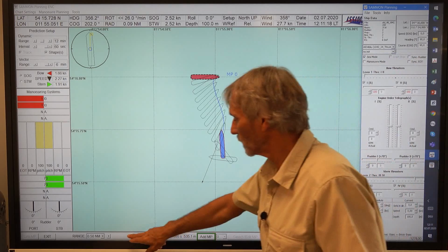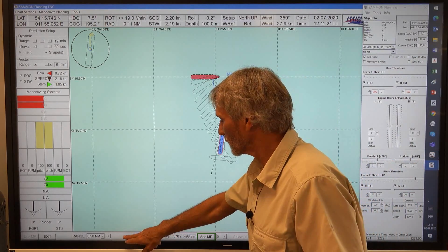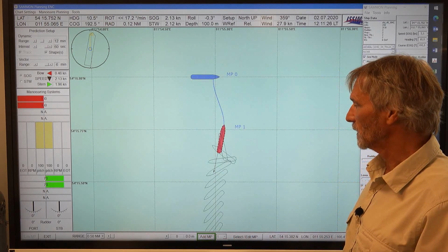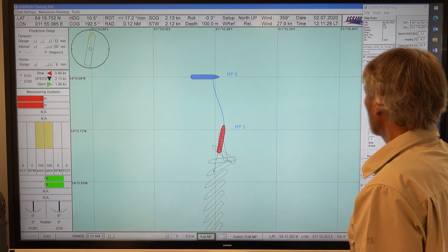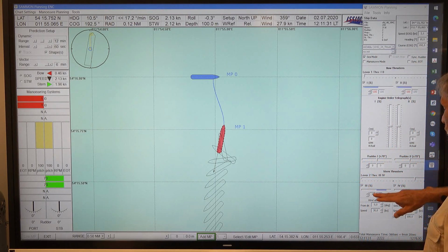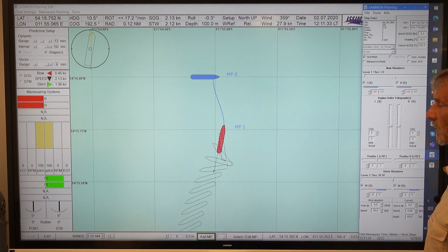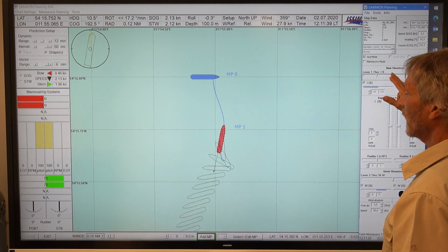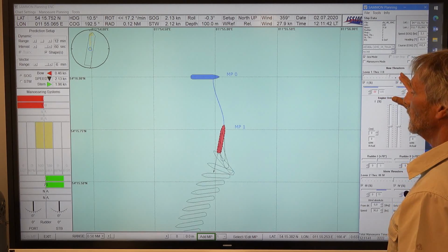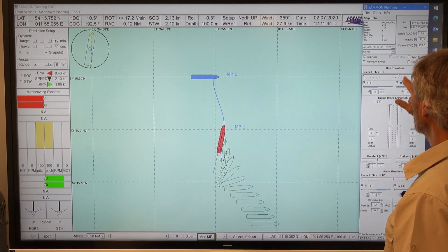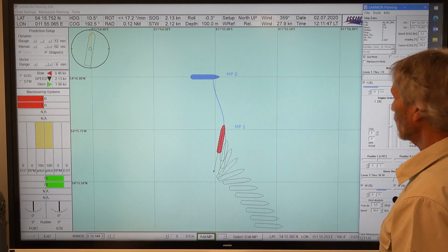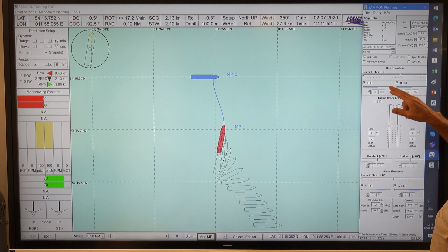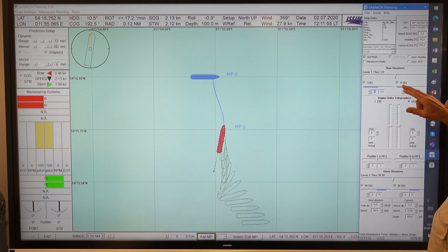If I go back a little bit until this position and I set a maneuvering point like this here, and then I switch off the thruster at the stern side, and I will adjust the bow thruster in a way that we can really keep the bow into the wind. So this is with only 20%, between 16 and 20, okay, this is no thruster.